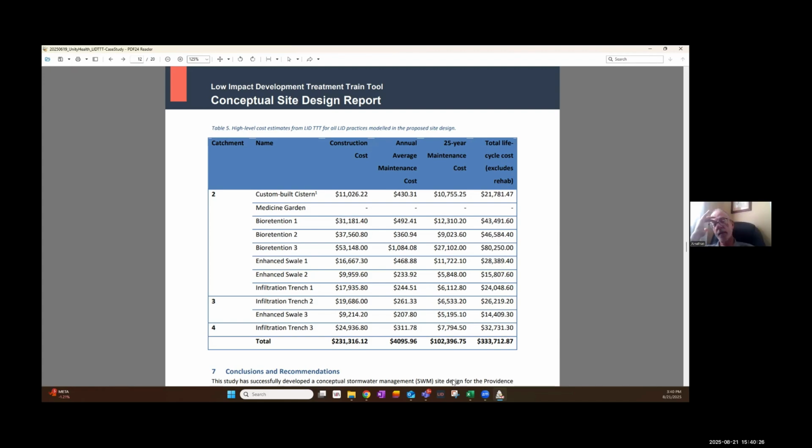Yeah. Okay, so this is very good. So I guess the next step here, James, you're looking at the hydrology performance inside the building, right? Yes. Right now, we have a rain gauge that tells us how much water we retain on the top of the building. In a simple scenario, if we have a storm event and we capture all of it, that's a certain impervious area that we know is not contributing to the downstream flow or to erosion, because it's lessening the peak flow rate and all that. We haven't modeled that yet, but that's the principle of the smart blue roof, and that's how we would go about modeling that.